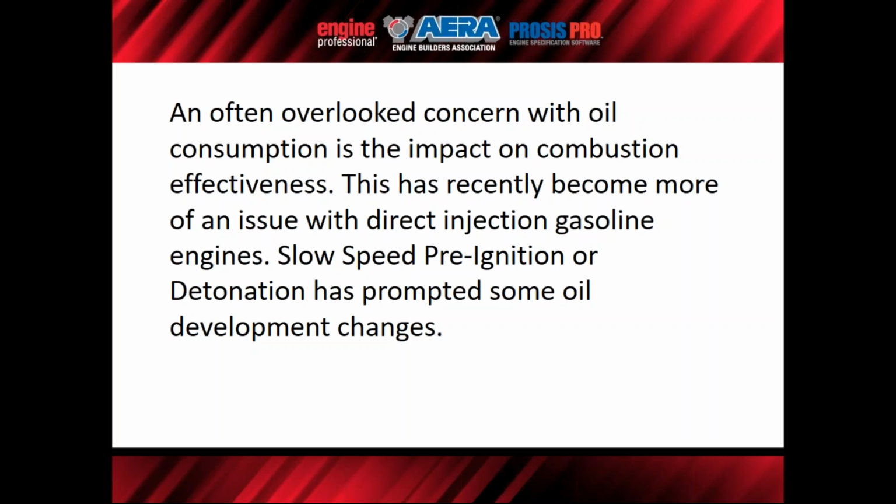They're trying to take advantage of higher compression ratios. So now you're having issues with slow speed pre-ignition, or detonation. Oil has started to have an impact on the burn rates, and because it's going to be in the combustion chamber, I have two sources of fuel in there now. There's a lot of people in the diesel world that would take used motor oil and blend it into their diesel and burn it in those engines.